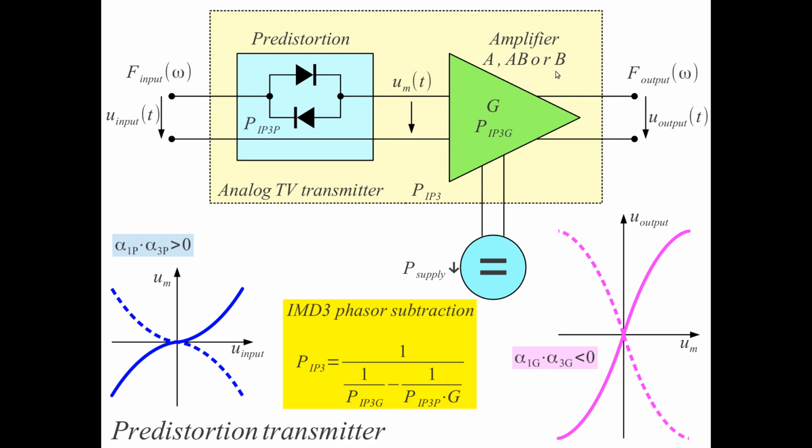Predistortion was typically used on analog television transmitters. It was something very difficult to adjust. With vacuum tubes in the output stage, it requires constant monitoring and constant adjustments. So it was a little bit difficult to use. Of course, we would not like that. It also depended very much on the impedance of the antenna, because all distortions, all the IMD in the final stage, these curves here, depend very much on the actual impedance of the antenna.